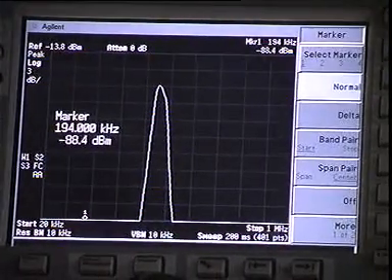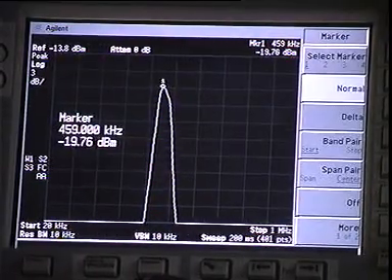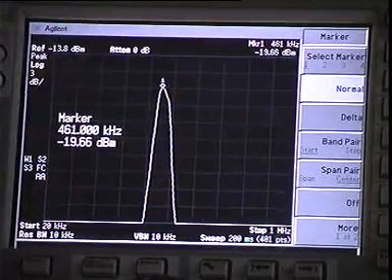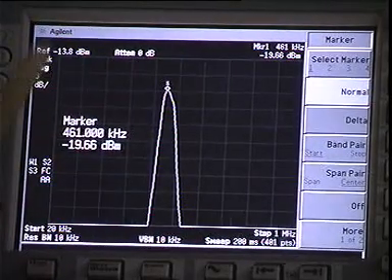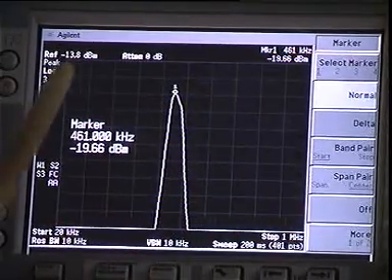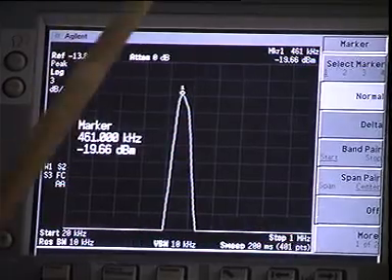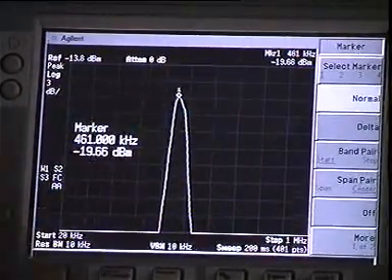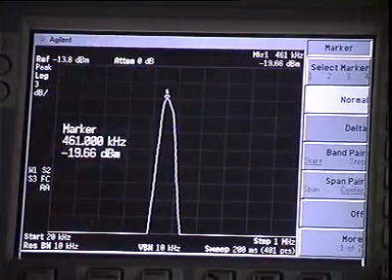So now let us go to the peak. Let us say it's minus 19.66 dBm. If I come 3 dB down on either side, I must read minus 22.66 dBm on either side. I should note the corresponding frequencies, and the difference between those two frequencies is the 3 dB bandwidth of this filter. So let us go on this side. I should read minus 22.66 dBm.